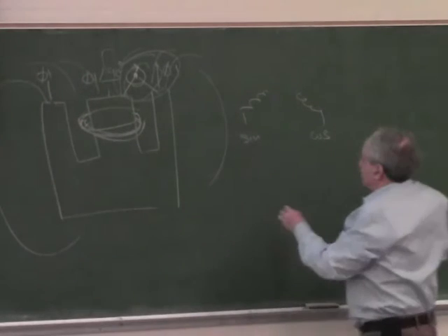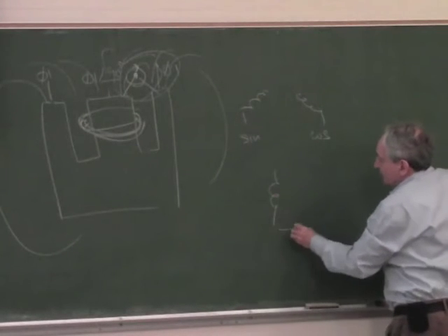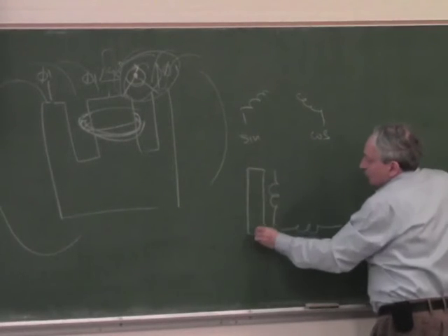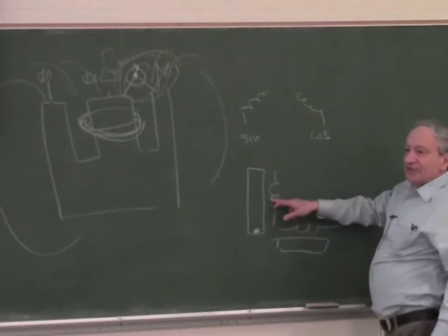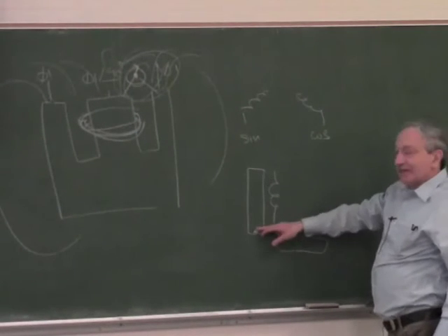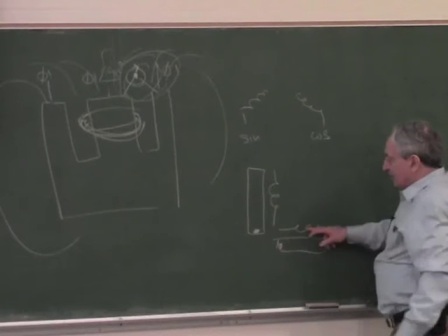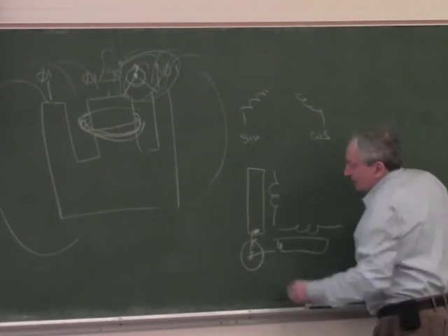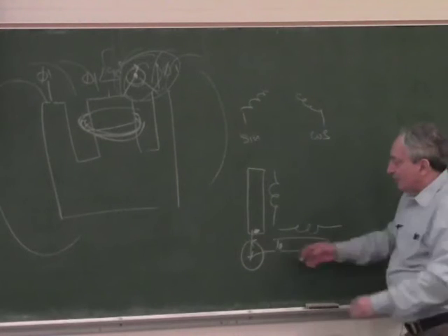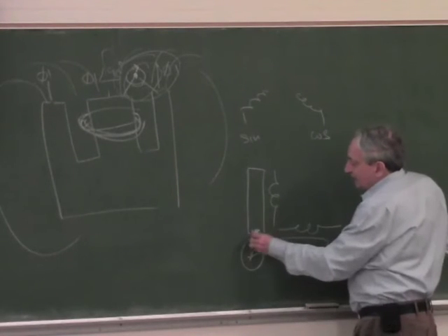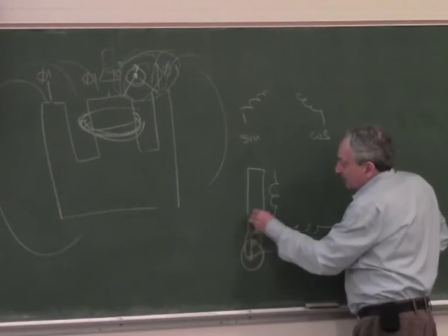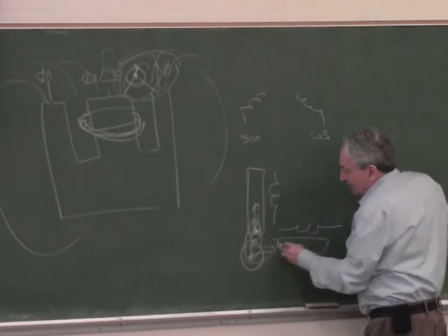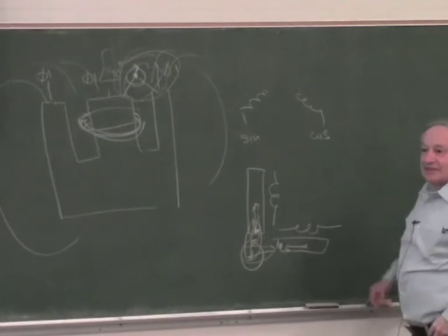It's the same in a two-phase motor. If you have two phases, and let's say they have iron cores, if you touch right here, you see mainly the field of this, so you see mainly linear. If you touch right here, you see mainly the field of this. If you stand here, you see a rotating field. But as you approach one pole, it becomes less and less rotating. It starts becoming elliptical until it becomes linear. And the same way here. If you approach this, it becomes elliptical. Inside here, it's linear. Okay?